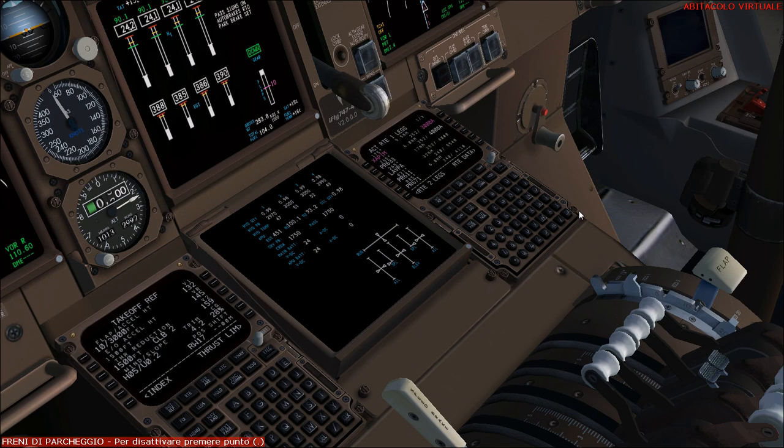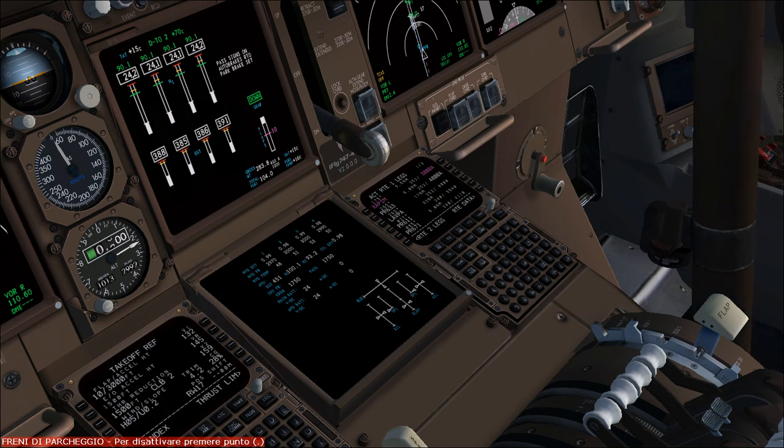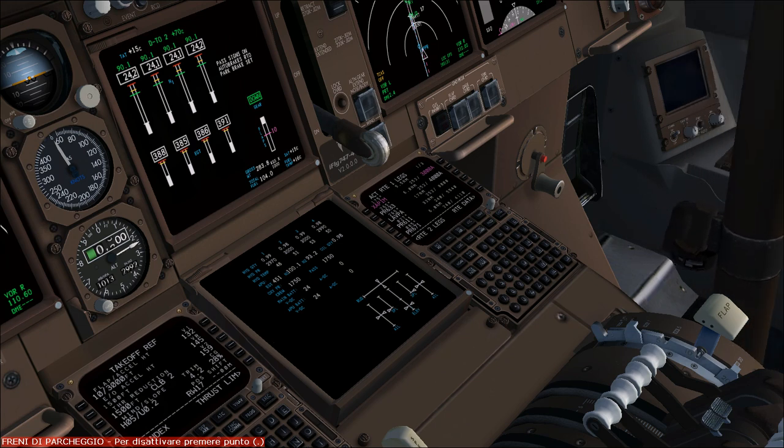Of course, I'm not using a joystick today because, as I said, I'm using a laptop, so I can move the rudder anyway. I can move the elevator. They are fine, and the ailerons. As we have the flaps down, the outboard aileron is working. When the flaps are retracted, the outboard aileron is actually blocked and locked into position.